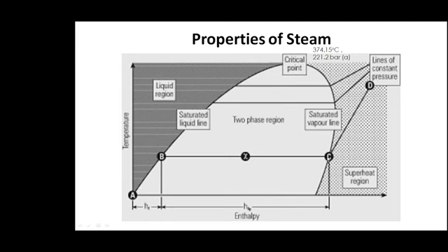Now, this is 100% steam that you have here, and this portion where a phase change has occurred is called the latent heat. When you take the steam into any equipment, the steam condenses, giving up this latent heat. So this is very important. We need to understand the fundamentals before we start saving energy. There are several questions we will be posing when we go to the industry, so understanding the principles matters.